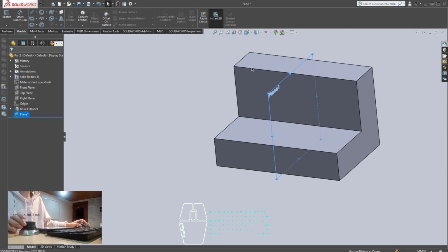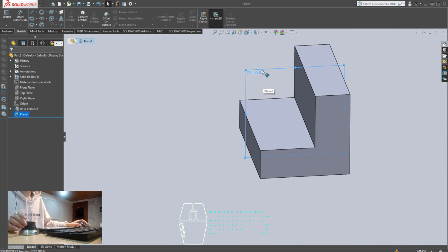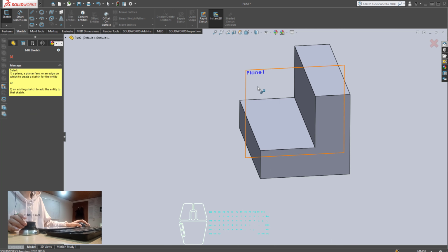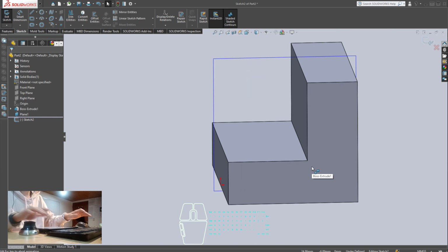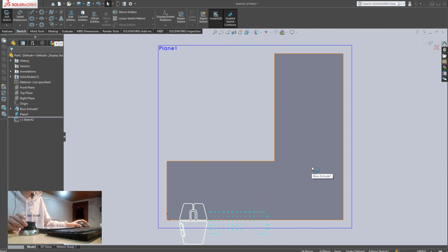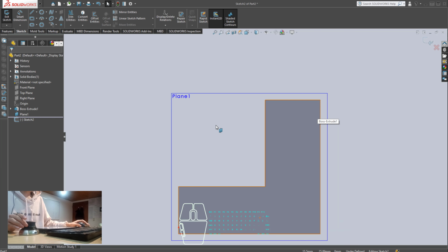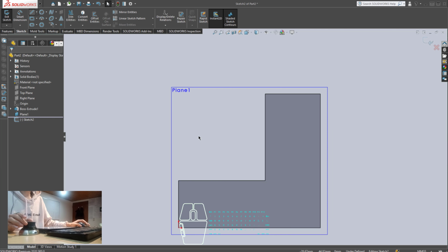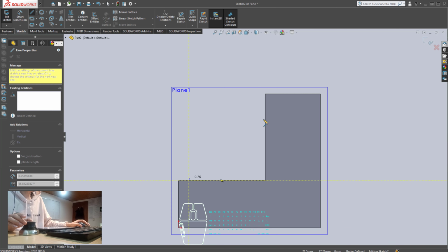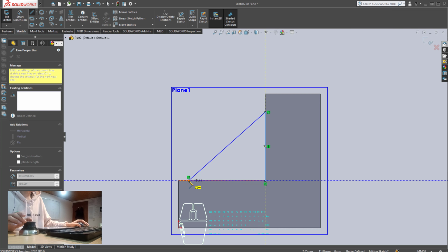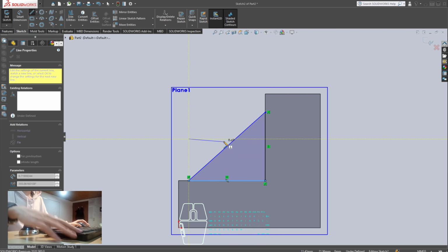Now I'm going to create a sketch taking into account this plane. Let me see, sketch once again, plane, right? Control 8 for me to be working in a perpendicular way. I'm going to disable the rotation. And basically, I just have to create the triangle. All right, escape.